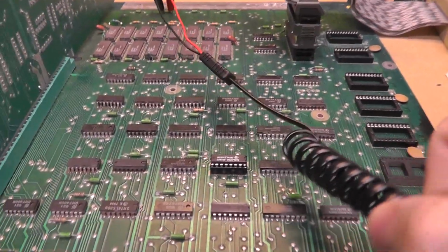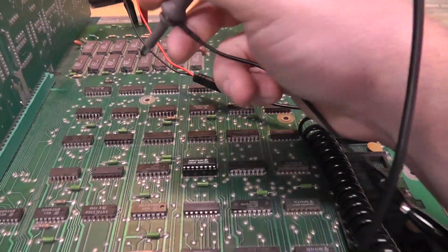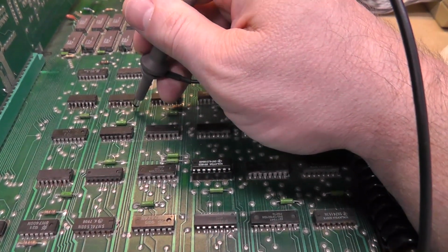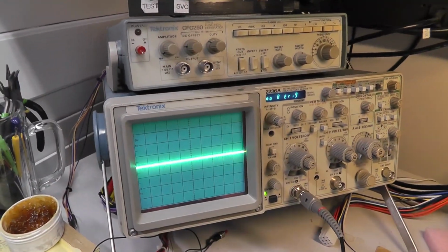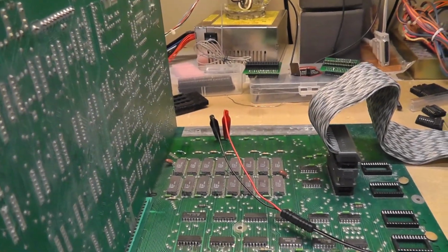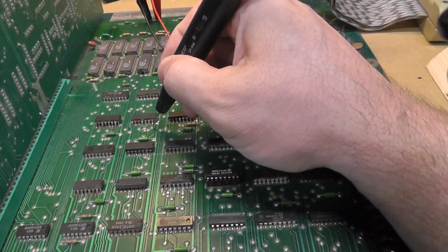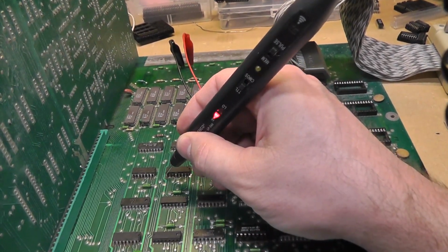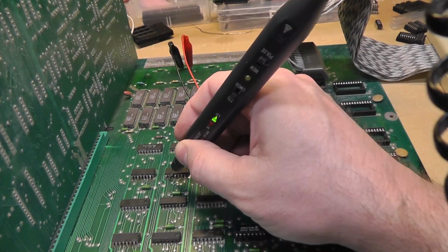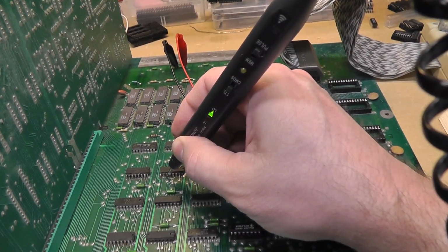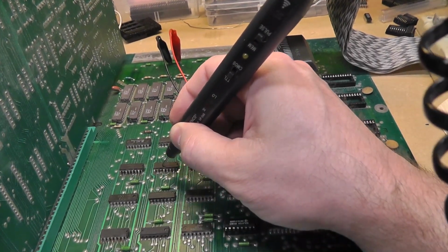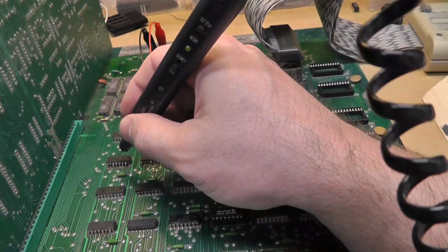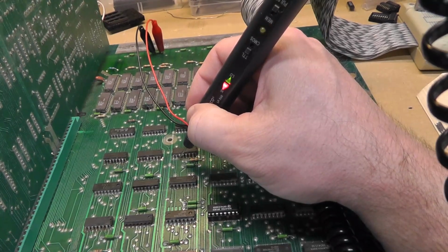All right, I was tracing things back and not filming everything, but I think I'm on to something. It brought me to pin 15 of these 9316s here, and it's just dead as a doornail. I went ahead and hooked up my logic probe just to make sure, and it's low. And I think this is a 9, 10, 11. This is a counter, the equivalent of a 161. That should be toggling. Yeah, something's jacked up. Here's another one right here.